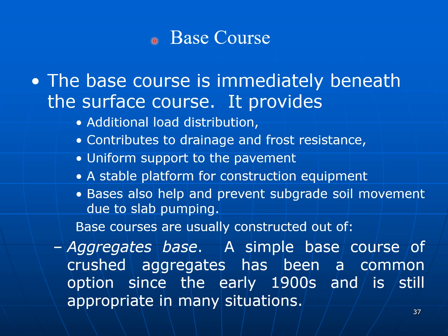Then comes the base course. The base course is immediately beneath the surface course. It provides additional load distribution, contributes to drainage and frost resistance, provides uniform support to the pavement, and a stable platform for construction equipment.